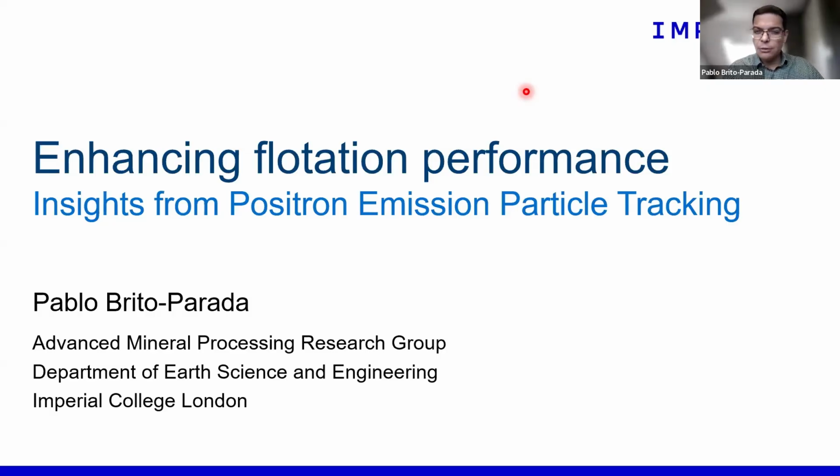With the tracers that we have used, typically we can run for about 3 to 4 hours, perhaps. Depending on the case, 4 hours might be a stretch, depending on the initial activity, but that's the usual length. So what we tend to do is to run continuously, and if we're testing different operating conditions, we keep recirculating the tracer for those 3 to 4 hours, until activity is low enough that data becomes meaningless. We still need to recover it in the end because there will be some activity. So we end the experiment and we start flushing the system with a meter that allows us to identify when it passes through, and then we put it apart until it decays. But yeah, that's a really good point.